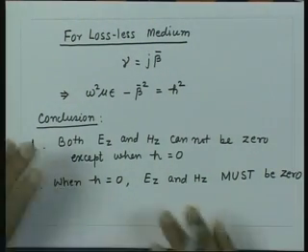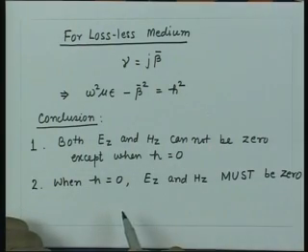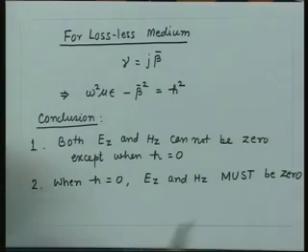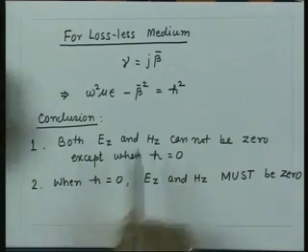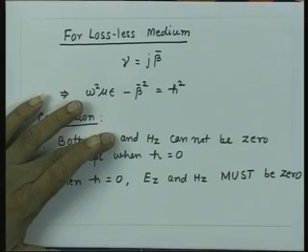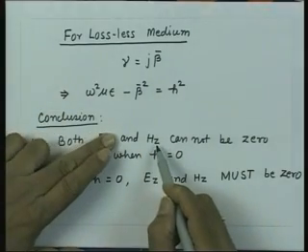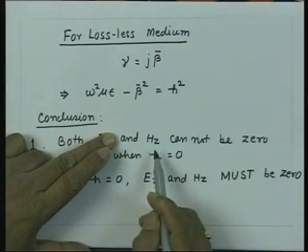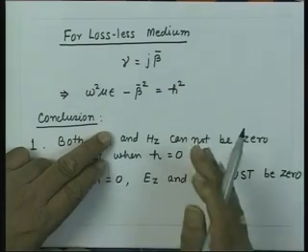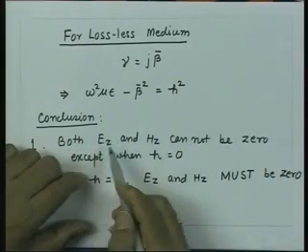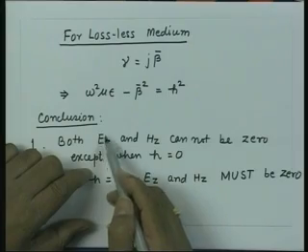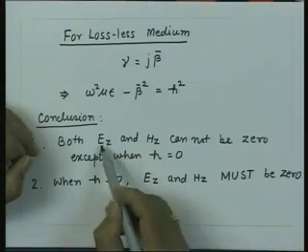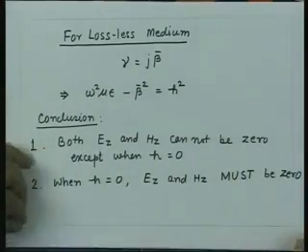So let us say first, if h is not equal to 0, then any of the quantities being non-zero will still give me the fields. So these fields will survive. Now if I take Ez equal to 0, I will get the fields which will be Hz and the transverse electric and magnetic fields. But for this situation, since Ez is 0, the electric field is completely transverse, because there is only the component of electric field which is E transverse, and this field configuration we can designate as a transverse electric configuration, as we have done in the parallel plane waveguide.